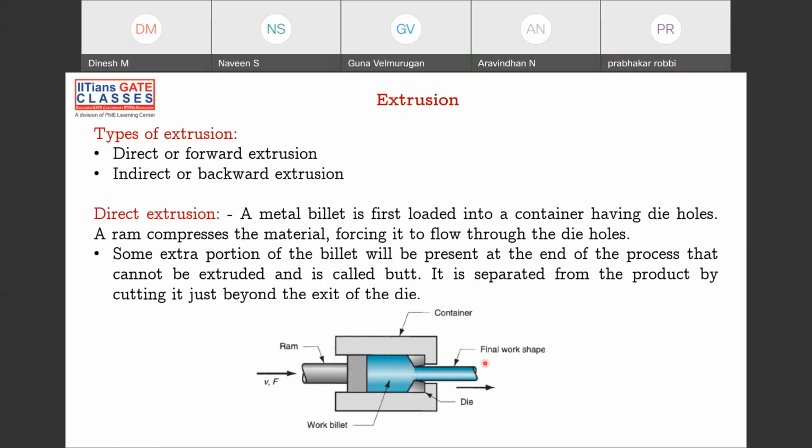Now, this is forward. The problem with forward is this circumference, if you see from the top view. That circumference has some kind of friction throughout, am I right? The friction between container and workpiece is there. This is where the friction, mu, will be. As the workpiece keeps moving and you push this side, the friction will be in this direction.